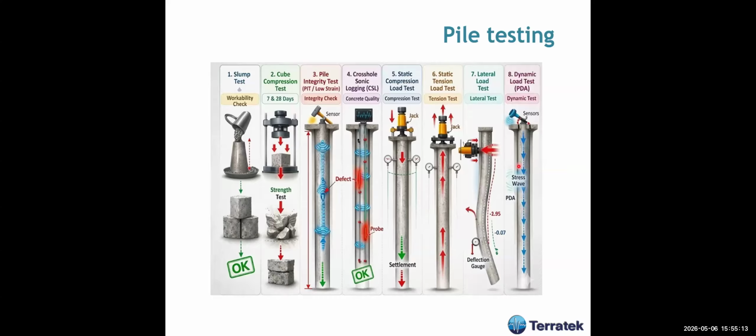What's the advantage of that? We measure the stresses during driving. This is very good for pile driving because we measure the amount of stresses, the tensile stress, the compression stress, and then we check whether or not the driving and the hammer are operating well and not damaging the pile. Of course, there is the expansion load cell, which is not covered here, but I've shown you before. So these are the pile testing methods.